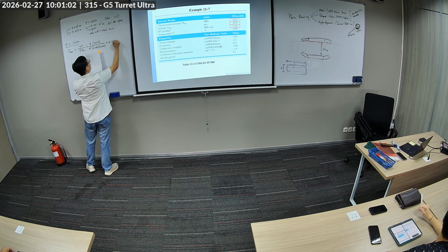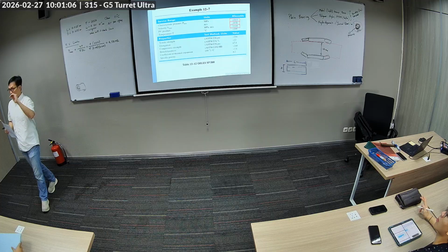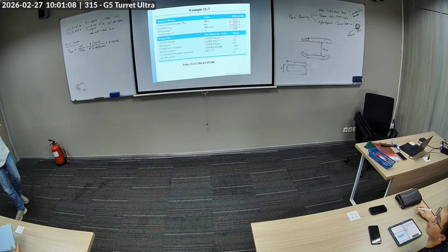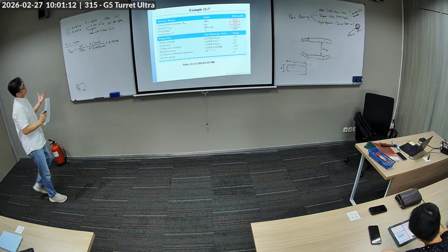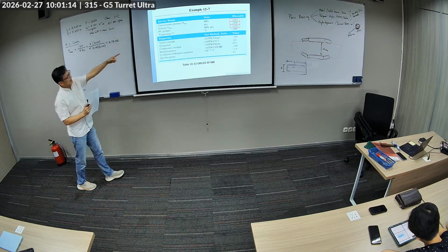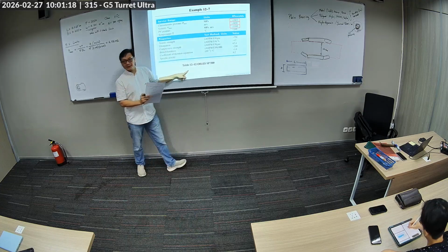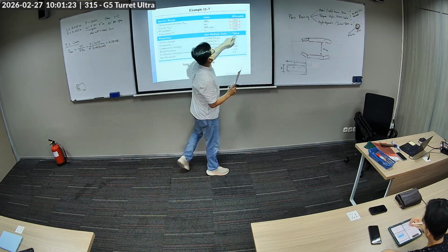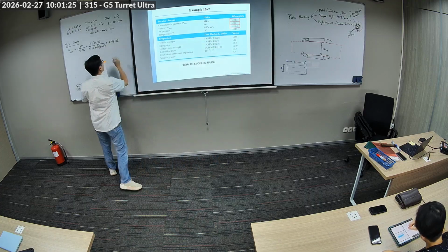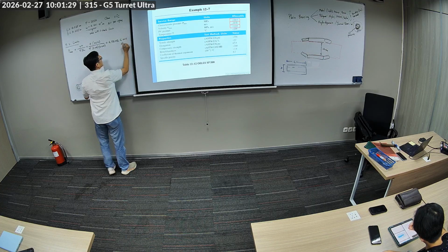So we have 4.58 megapascal. Pascal is Newton per meter square. So megapascal, 10 to the 6. Now we have the limit here for SP500 oilless, which is a brass bushing. The limit is 24.5 megapascal. So this is less than 24.5. Means it's okay.